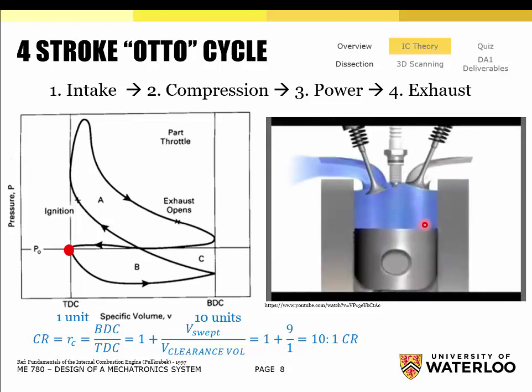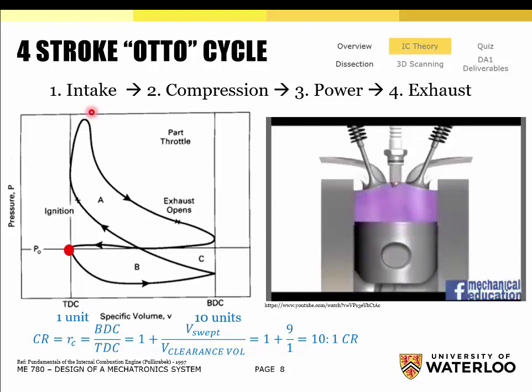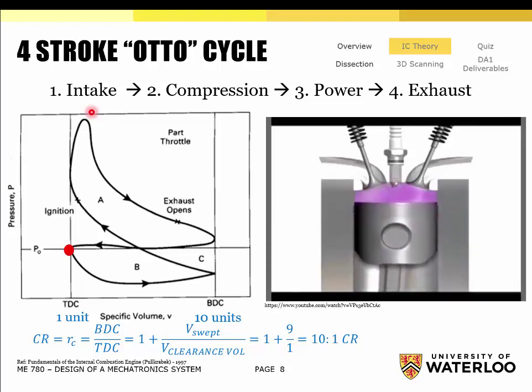Okay, so the peak of this curve will go up. This is a really excellent question because this is how you can determine the difference between a high performance engine and an economy engine, and how they work in terms of a pressure volume loop. Okay, you can get more usable work out of a higher pressure engine. So the peak pressure here will go up when you turbocharge, but what happens to the exhaust gas?